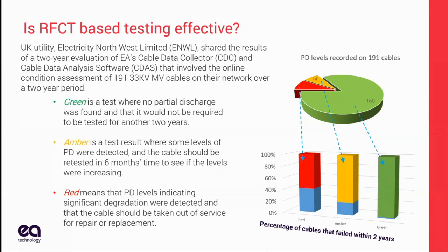And if they had done the yellow and the red, they would have gone even lower. So as you stand there and you look at 191 cables, I don't know what to do. I don't know which ones are going to fail. I can't take an outage on any of them. I'll do nothing. That's what happens. Here, I do the test. The test is quick, easy. The repairs may not be, but it's always preferable to do a repair than to wait until it fails and then get called out in the middle of the night, because like babies, cables fail. Cable failures come in the middle of the night.